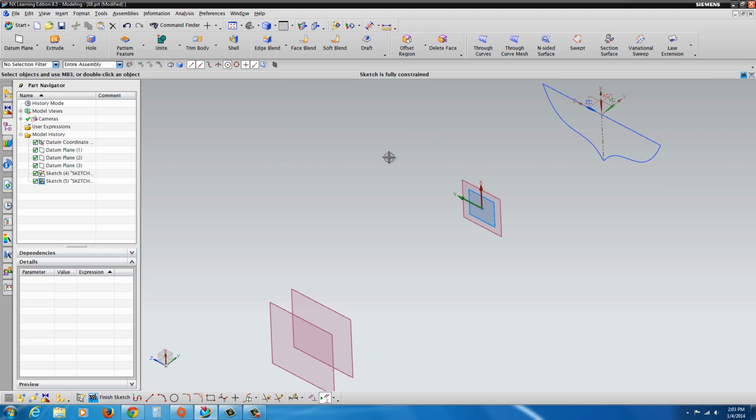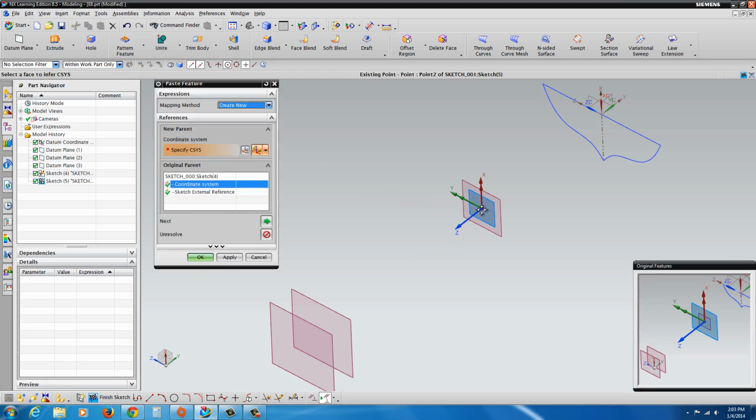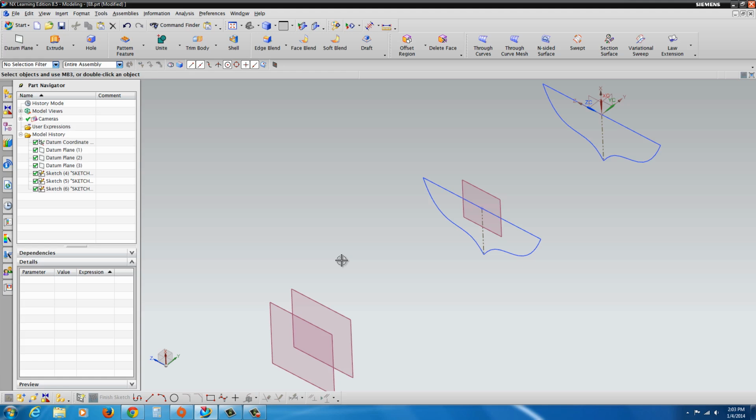Okay, hit close, and actually what I want to do is grab the sketch over here, sketch 4, and select copy. Now you could go to paste and drop it in on that point, and hit OK, and it should drop in there. Now, I selected inside there the paste. There were some options. If you just go with the default, you're in good shape.